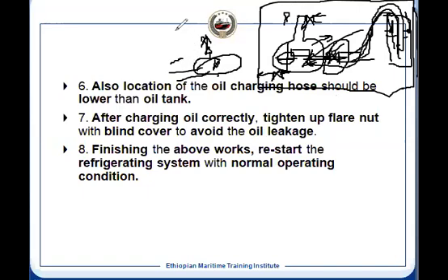Understood? So cut off pressure, or you can reduce the setting. Both ways. You can reduce the setting to zero, but you are doing it for the refrigeration and air conditioning system, you are doing it manually. Usually, refrigeration systems don't cut in and cut off. It's continuously running. And in fact, that is the reason you can change the setting to zero bar pressure. Clear, understood? Yes, I understood. It's clear. So any other questions till now?